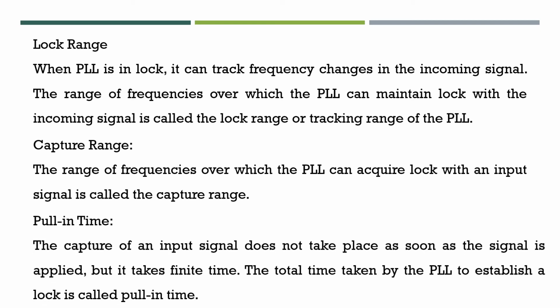And the next one is the pull-in time. The capture of an input signal does not take place as soon as the signal is applied, as I have termed. Initially we apply the input, so there will be no lock condition occurring, but it takes finite time. The total time taken by the PLL to establish a lock is called the pull-in time.